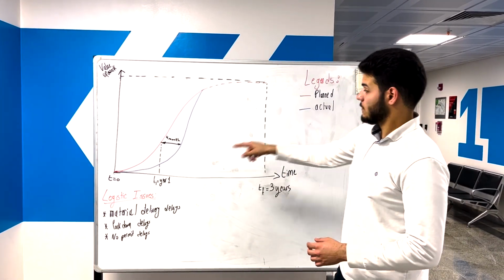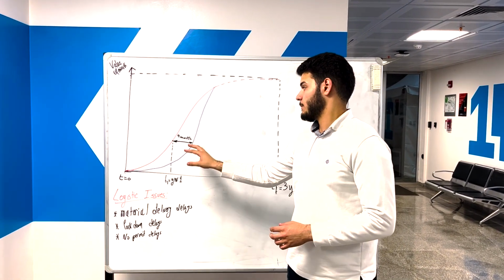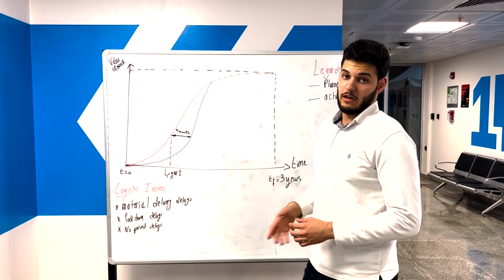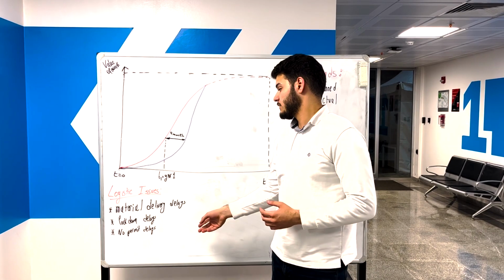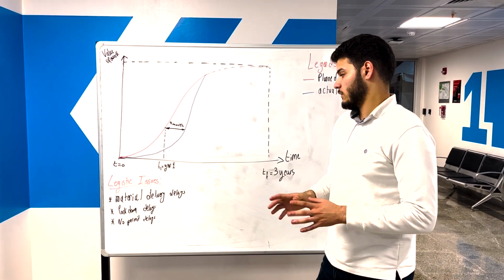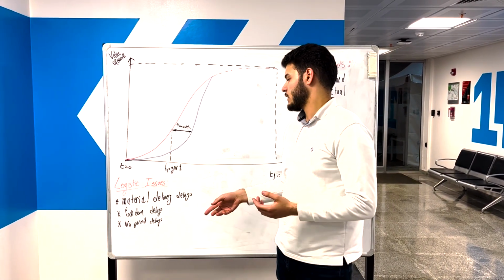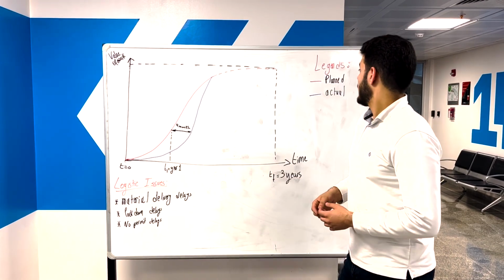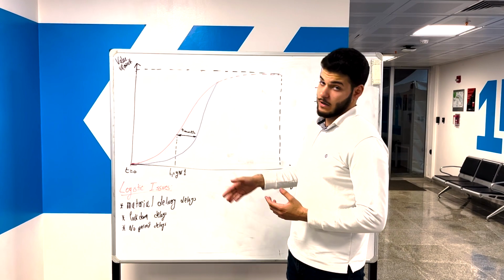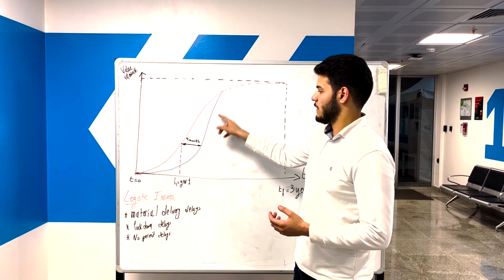As for the S-curve, which plotted the value of work with respect to time, it shows the planned value, which is represented in the red, against the actual value, which shows a delay of 4 months starting at year 1. And that's mainly due to some logistic issues, which are related to the material delivery delay and the lockdown delays, and actually there were no permit delays. It was safe from that side. The material delays were mainly due to COVID-19, and the lockdown delays prevented them from working. But they compensated for the lost time by doing extra shifts, and it's reflected in the sharp slope increase in this curve.